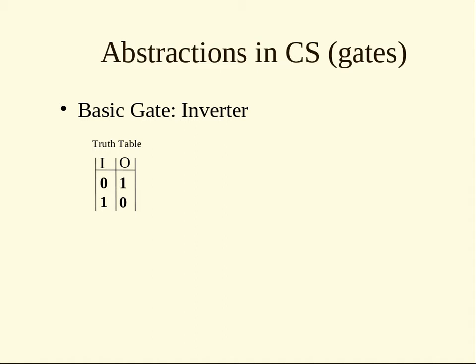So the simplest one is called an inverter. The idea is that if your input is a 0 bit, the output is 1, aka if you have no voltage coming in, it produces voltage coming out. On the other hand, if you have voltage in, it produces no voltage coming out. All right, inverter. What is this in C? Exclamation point. Yes, it's the NOT. All right, seeing where this is starting to connect? How do we make a NOT inside of a circuit?